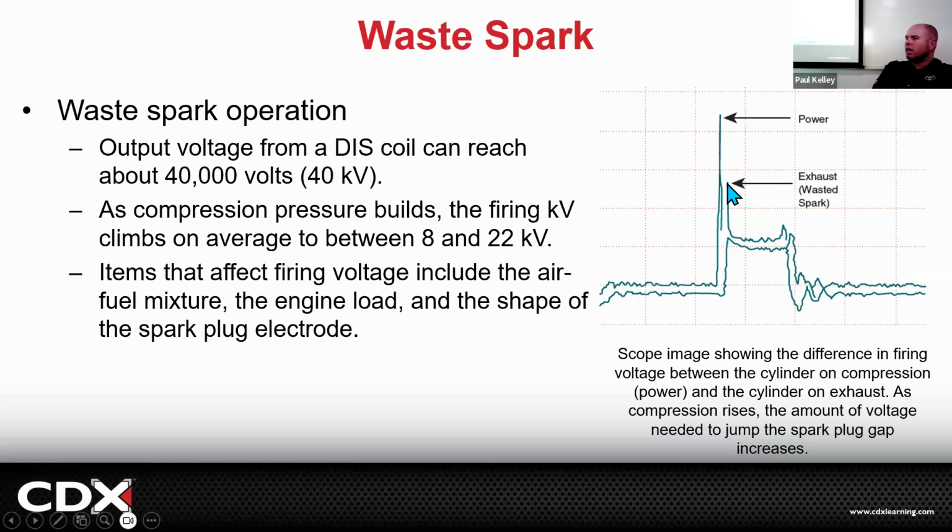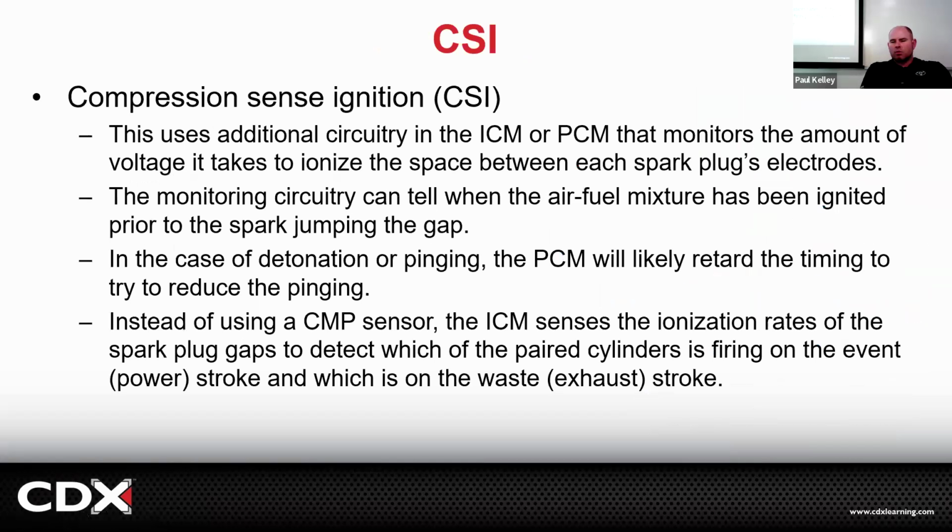So sometimes you just got to know which waveform is your actual one you're worried about. We're not really worried about the waste spark because that's on exhaust. We are worried about the power spark because that's on the combustion to the power stroke. It's kind of unique.